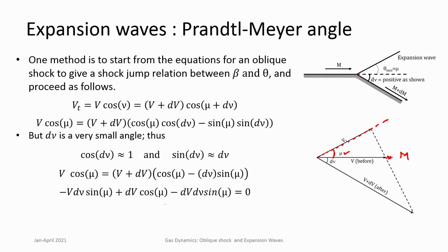With respect to this Mach wave, you draw all the others. As the flow goes through the Mach wave, it undergoes a very small change in angle, d nu, and a small change in velocity, V plus dV.